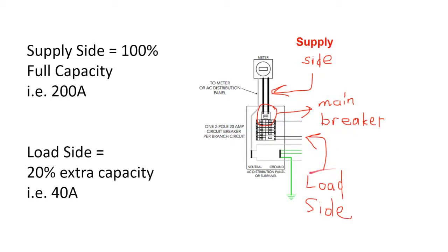Interconnection options are available either as a load side or supply side connection. The supply side connection is located between the customer meter and the main service panel. The supply side connection can equal but not exceed the rating of the electric service.